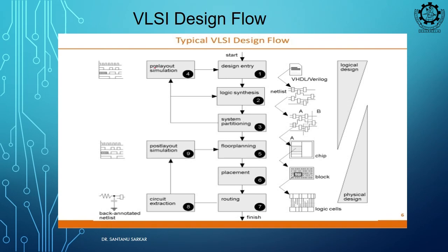We have pre-layout simulation or schematic simulation, and we have post-layout simulation, that is considering the physical. In this post-layout simulation we will do the circuit extraction or parasitic extraction, and we consider all the RC circuits and combine them to get the timing.